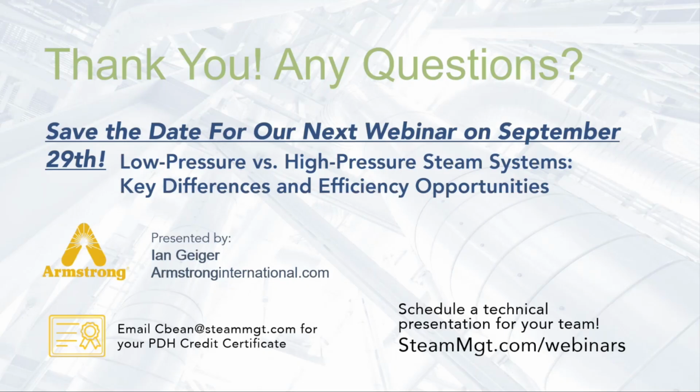Yeah, interesting. So that would really only work for monitoring for flooding, and it would have to be low pressure to use the conductivity monitor. So the air handler is probably the most common application that makes sense, and we've seen that time and time again. Many customers are really concerned about freezing coils, or if it was some other critical process on a heat exchanger that was at a low supply pressure. Absolutely. So that could be possible.